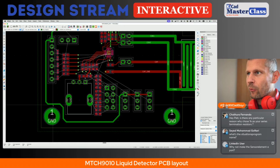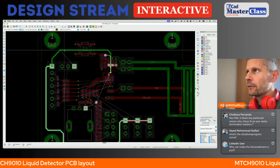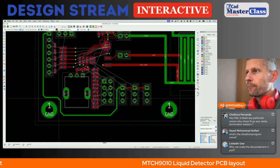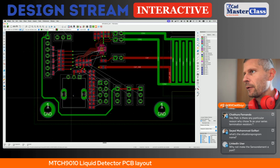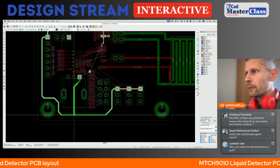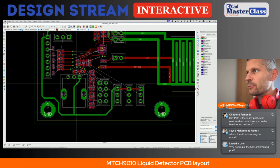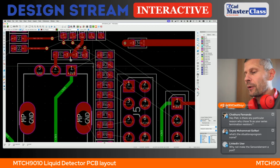All here I want to have the reference plane. So I have to keep the possible pathways for the reference plane as thick as possible on the bottom layer.